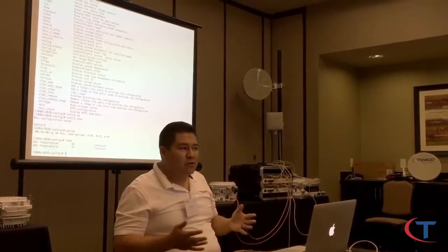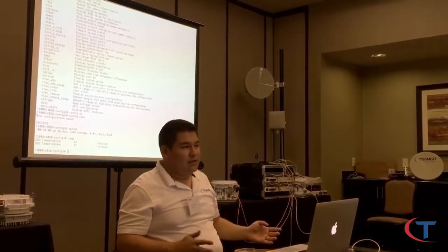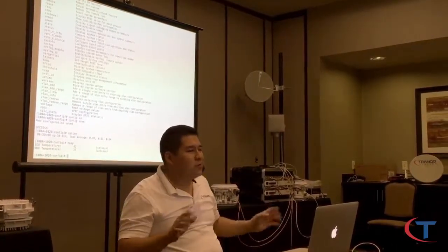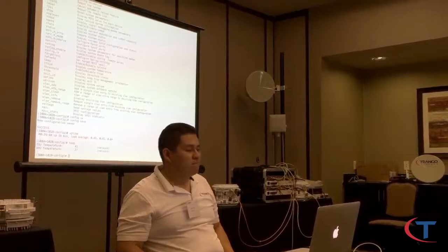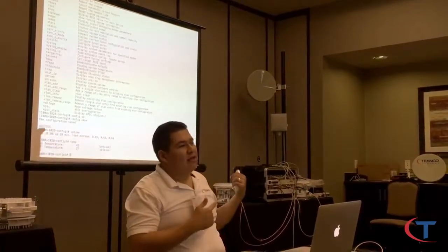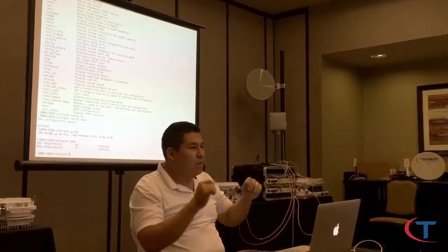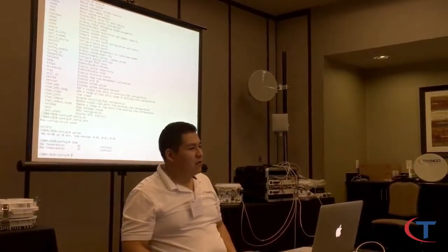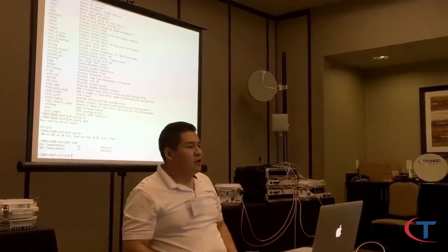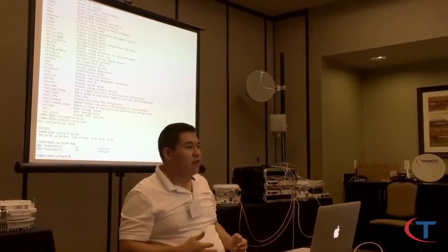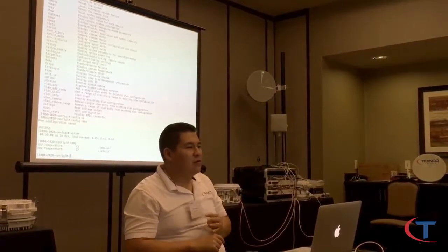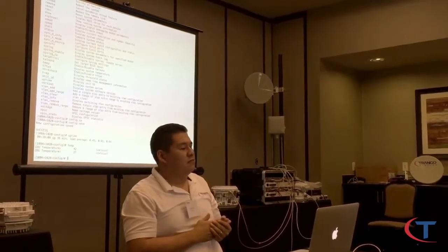After a couple hours, it unlocked again. I said, okay, I know what the problem is. It's my far side transmitter. The ODU has to be bad. I go up to Black with another ODU, swap it out, and the same thing happens. Wow. So I take a look at the inside of the ODU. With my privileged user from Triangle, I can see everything is fine. Receive signal, power coming out, but it still unlocks on me.